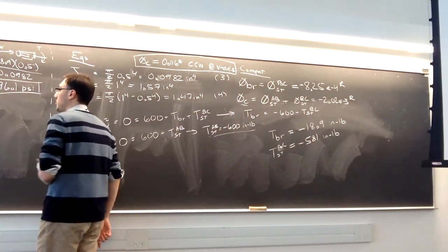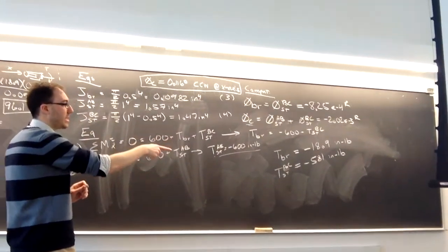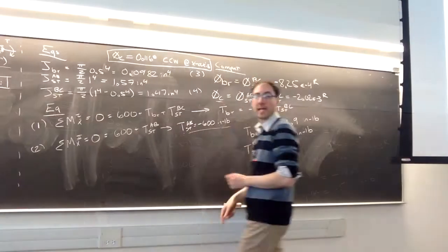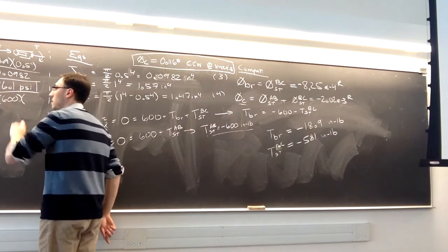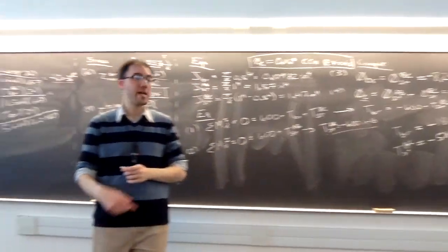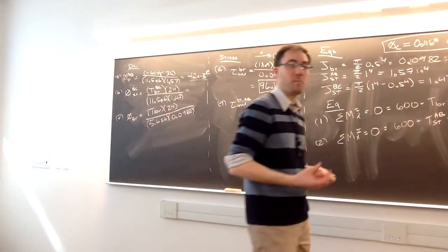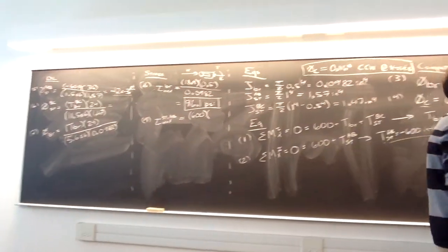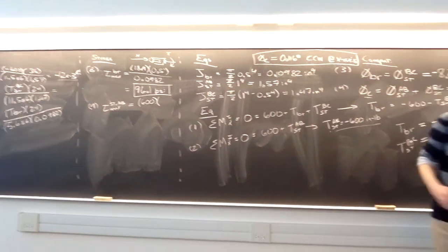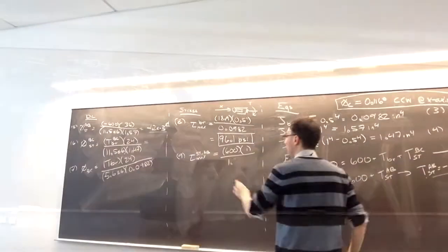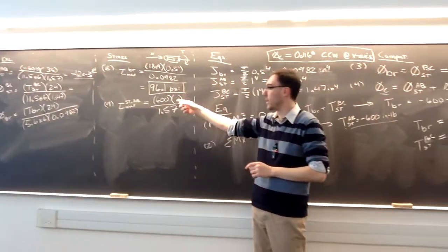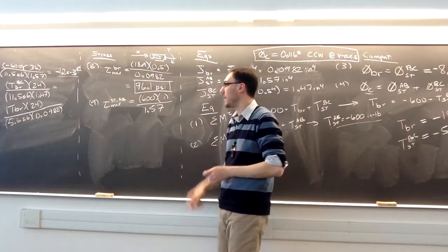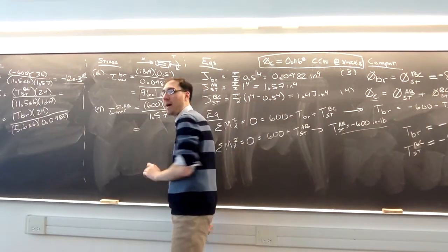In the AB section, we have an internal torsion of 600 inch-pounds. The steel section in AB, even though it's hollow, the maximum will still occur at its outside radius. For this piece, that's going to be 1 inch. It is 1.57, right? Just looking at it backwards. Right, so the solid section: outside radius 1 inch, J of 1.57, internal torque of 600 inch-pounds.